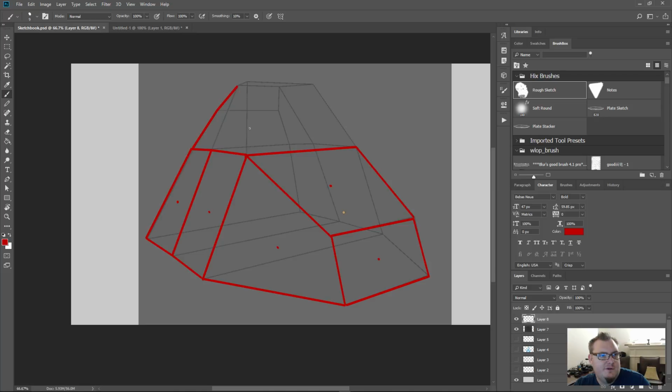This is a little confusing if you are not paying attention, but you should be able to tell from the way this is constructed what should be in front and what shouldn't be. So this is going to be drawn straight down. That's a face. Here to here to here is another face. This is pointed up towards the sky, so you're not going to see that face. And then we've got the rest of our silhouette in here, so this is just one big face right here. Everything else we leave blank.